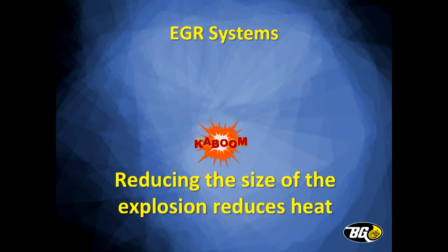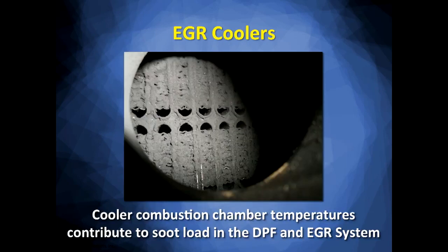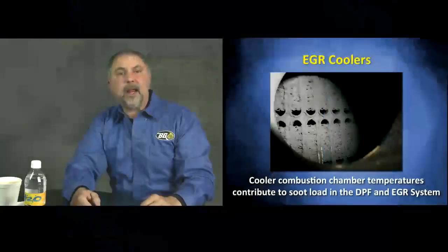But going back to what I mentioned earlier, you're dampening that fire. So you may have soot that starts to accumulate in these EGR and EGR coolers, because again, it has to head out to the tailpipe. So our manufacturers are scratching their head, how do we circumvent this? And we got guys putting delete kits on it. Please don't put delete kits on these EGR systems. It's illegal. 1990 Clean Air Act.